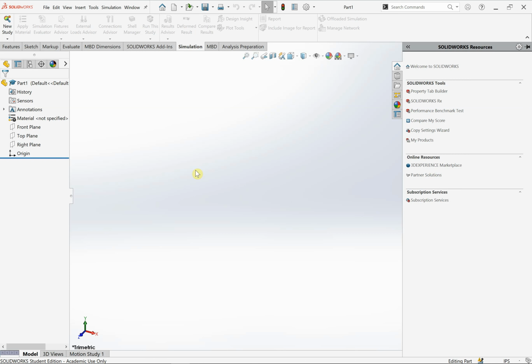So there's at least 3 mode shapes for this beam. You can look in the book. We are in the FEA book again, or your vibrations book. For the system, we are considering our natural frequencies would be 19.71 Hertz, 121.85 Hertz, and 341.22 Hertz. If we put the mass on the end of it, we'll get some slightly different numbers. The book also has